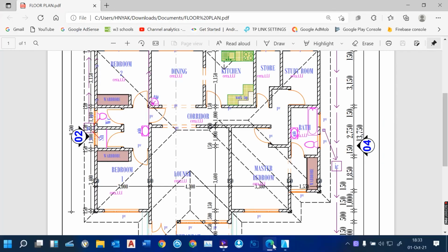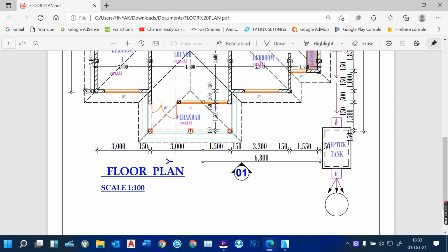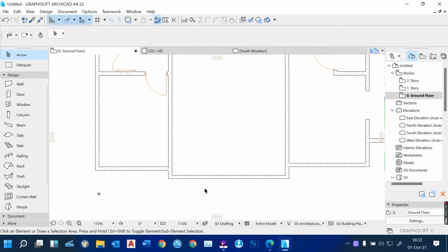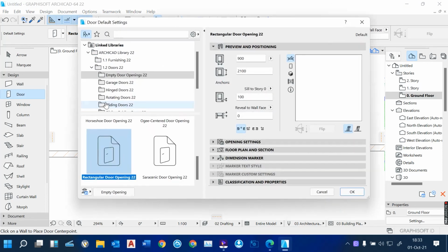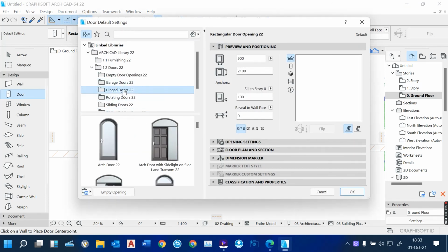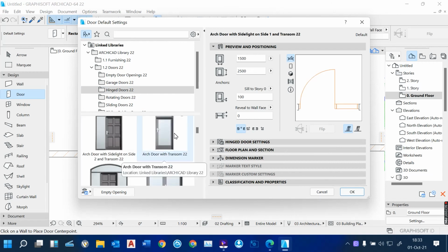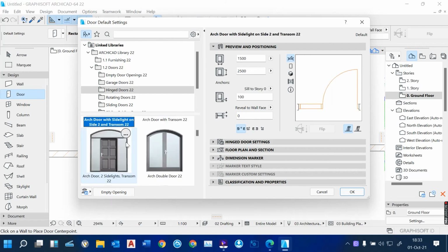When you look into our drawing, we've got our doors placed. Then you also have this type of door for the entrance. You also have to place it because this was a permanent ventilation. So you pick a different type of door, double click on the door tool. Then we've got various types of doors. So it's a double door, so just click. You can click and see how it looks.